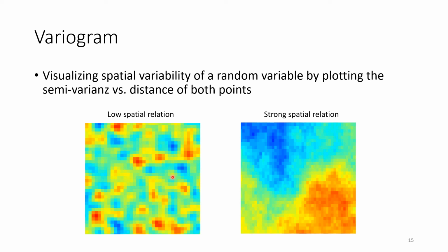So you can generate random maps of random distribution, for example of hydraulic conductivity, but incorporating at least the variogram information that you have, knowing like, okay, here I'm expecting really strong contrast on a small scale, so you can generate random maps with that information.